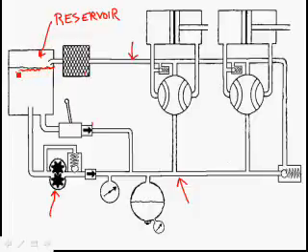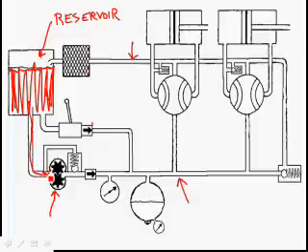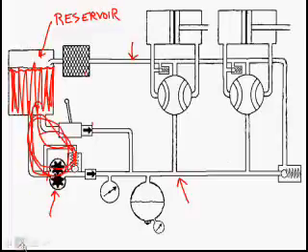You'll notice here's the fluid level. So here's the fluid. You'll notice the fluid comes out of the reservoir and goes to the engine-driven pump. I have seen some systems where the pressure relief, or correction, the pressure regulating valve sends the fluid back to the reservoir, but still, we'd still be running the fluid in a circle.